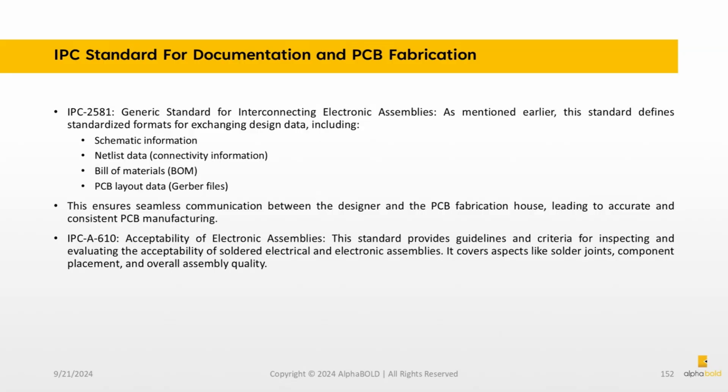IPC A610, Acceptability of Electronic Assemblies. This standard provides guidelines and criteria for inspecting and evaluating the acceptability of soldered electrical and electronic assemblies. It covers aspects like solder joints, component placement, and overall assembly quality.